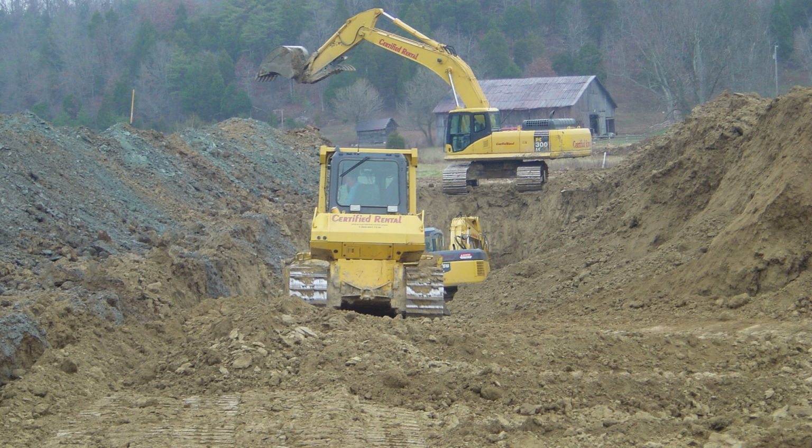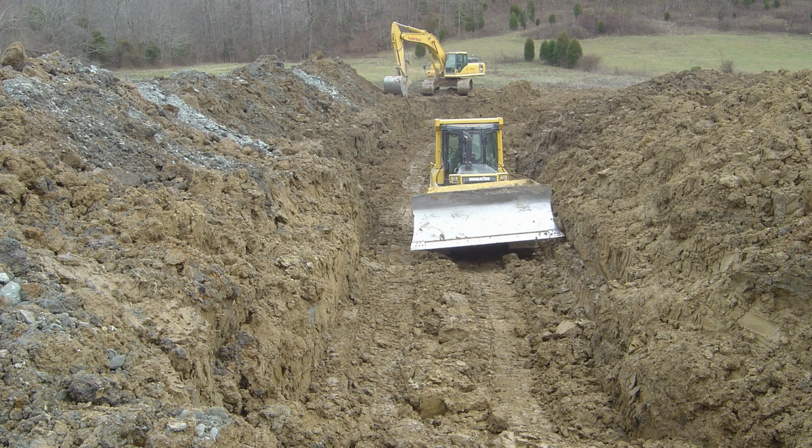The dozer operator is pushing silt clay soil towards the excavators that will be placed in the bottom of the core trench. The dozer operator travels back and forth and from left to right to compact each layer of soil that's placed in the core trench. The trench was dug wide enough for the dozer operator to move the machine from left to right to compact even the center of the soil that was placed in the trench.